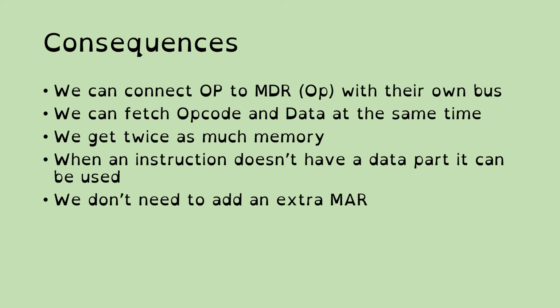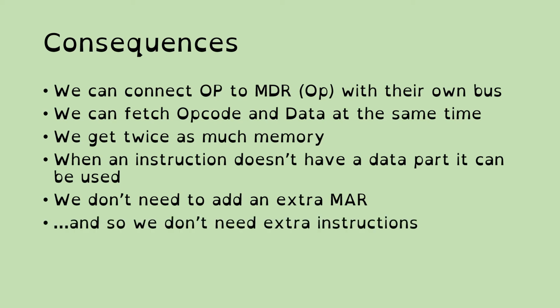So you might say, why not go a little bit further and just have an extra memory address register and do them separately? And the reason behind that decision really is that we're already full with our opcodes. And so if you add another register, you're going to need more opcodes to deal with it or sacrifice some of the ones that we've already got. And actually, the downsides of doing it this way are not huge, and the upsides seem to be quite good, specifically when we're dealing with 4 bits, because I'm not sure that I would approach it in this way if I was going for 8-bit or larger.